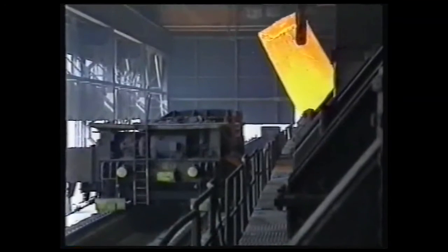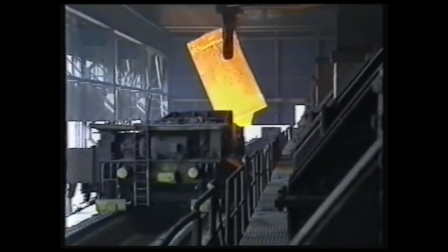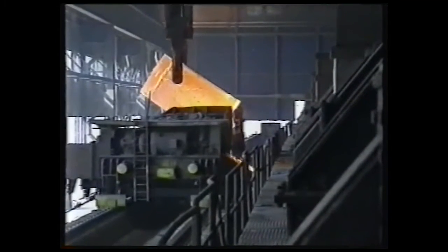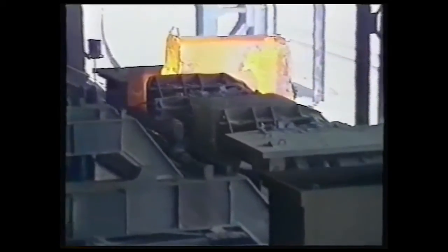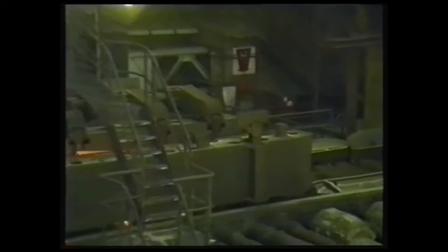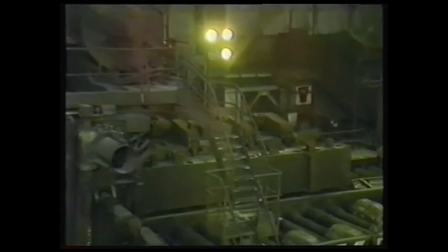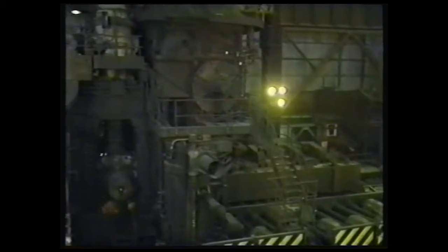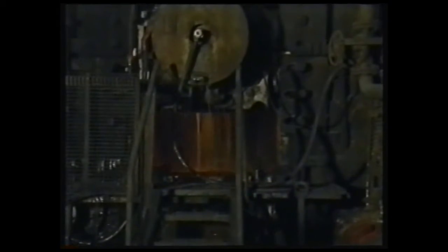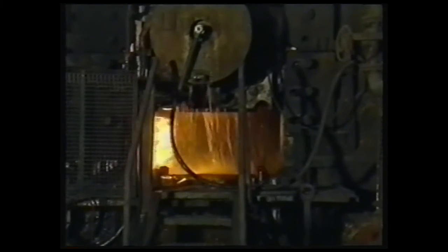The input of the hot rolling mill consists of slabs and ingots of several tons. Slab thickness is between 150 and 230 millimeters. The produced coils after hot rolling, on the other hand, have thicknesses between 1.25 and 12.7 millimeters. This reduction is realized in several stages. An initial thickness reduction of the slabs is realized in roughers. Further rolling of the material is carried out in the finishing mill.